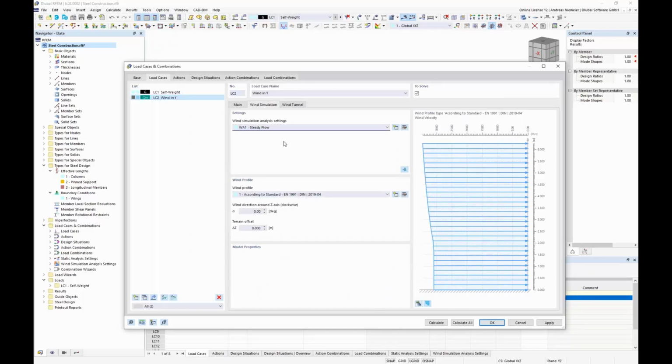Then we specified how the calculation should be done, but the question is, with what the calculation should be done. We know CFD calculation is something like a numerical wind tunnel, and we have to give the program the feedback what he should send into the wind tunnel. Of course wind, but with which speed. And here you get an option to set a wind profile as boundary condition for the wind tunnel.